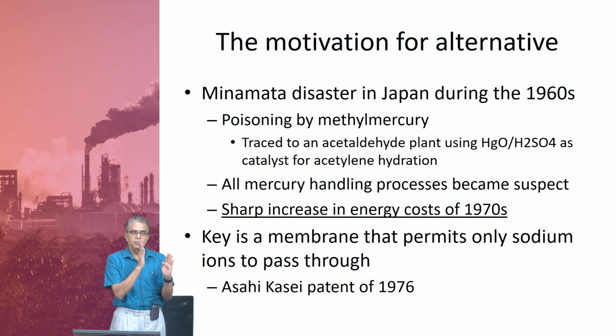Okay. If you are able to break that, which means is there any other non-mercury electrode which will allow this reaction to take place at a lower potential, then you have got a good thing going. The logic is very clear. So, one possibility to look for is that we got this energy because of mercury, and mercury is required because it is a beautiful thing, it works, it picks up electron, transfers to sodium without messing up on water, it can be separated, it flows also very nicely.